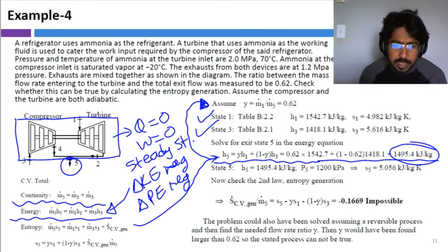Specific entropy generation, we don't have a parameter defined under that name, but entropy generation per kilogram is what we calculate here. Because entropy generation divided by a positive quantity doesn't really change the sign, whether it's possible or impossible, what we are interested in seeing is whether it's positive or negative.